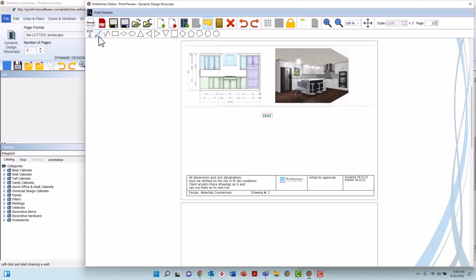To use a single line, left-click to grab, left-click to drop on a page, drag, and left-click to secure. The multi-line tool is also selected with a left-click and placed with a left-click. But with this tool, you may drop as many connecting lines as you want. When you are done drawing the multi-line, tap the Escape key to release.